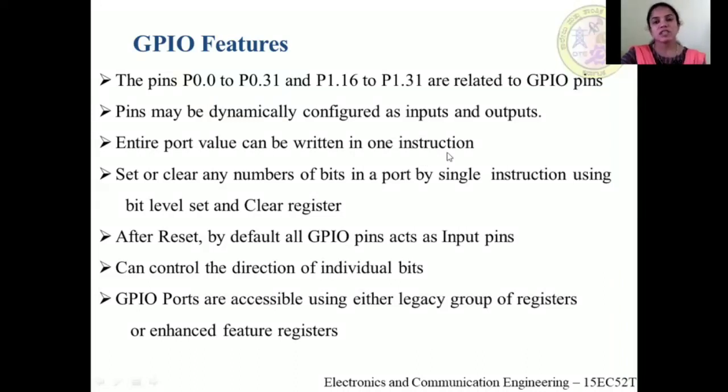There are some sets of instructions used to access these port pins using only one instruction. Either we can read or write all the data at a time into the port pins, or we can set or clear any number of bits in a port by a single instruction using the bit level set and clear register. So there are two options.